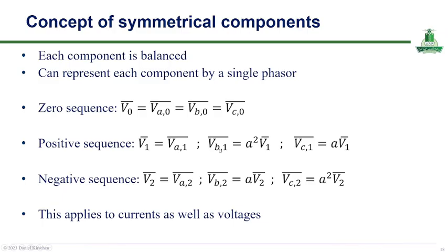In this slide, I want to introduce the concept of symmetrical components, which is, as I told you, a powerful method for analyzing unbalanced three-phase systems. The key idea is that any unbalanced set of voltages or currents can be decomposed into three balanced sets of phasors: zero, positive, and negative sequences.